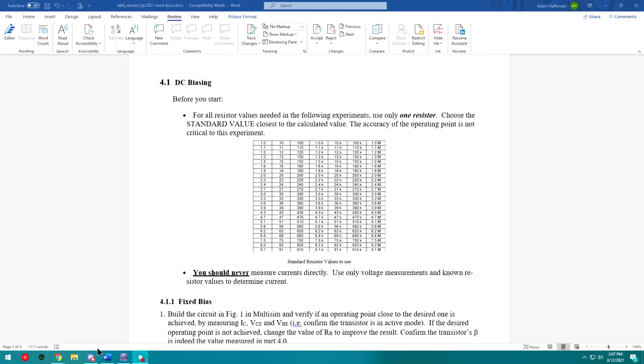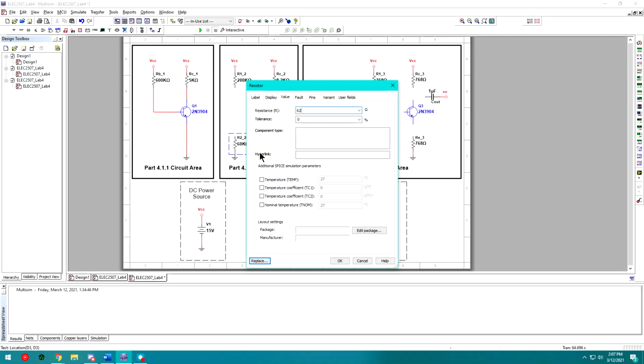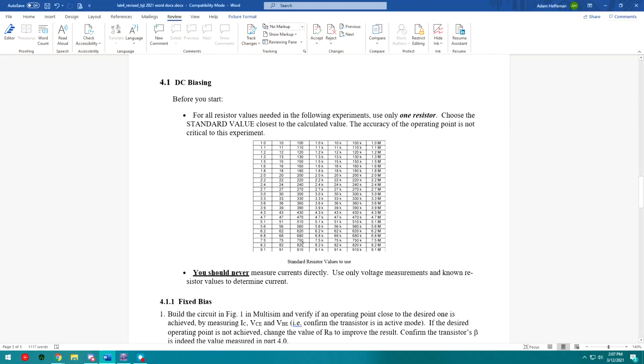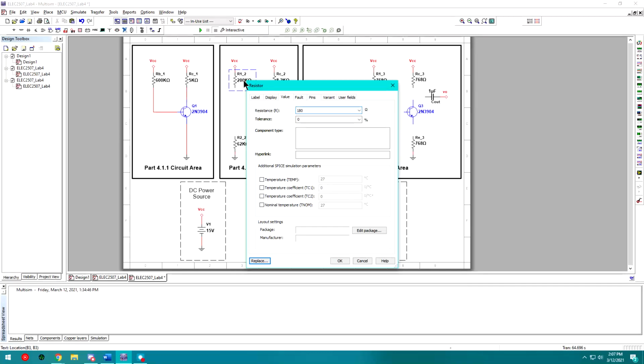Yeah, so actually I should have chosen a standard resistor value for my R2. So I'm actually going to switch that to 62K. And then from there, I calculate that my R1 should be around 181 kiloohms. So let's find the closest standard value again and find that it's 180K. So go right here and switch this to 180K.